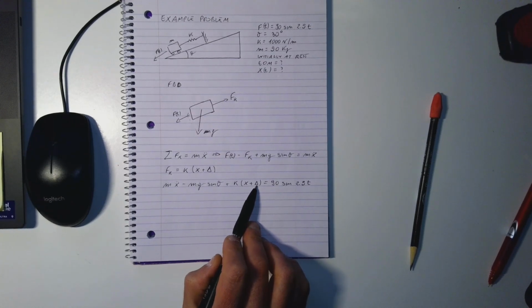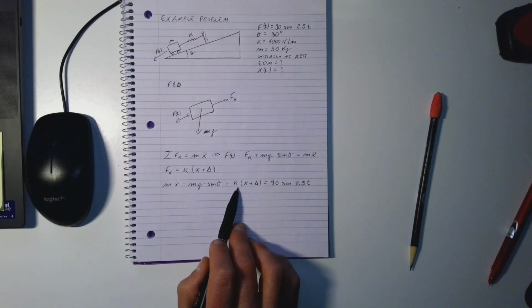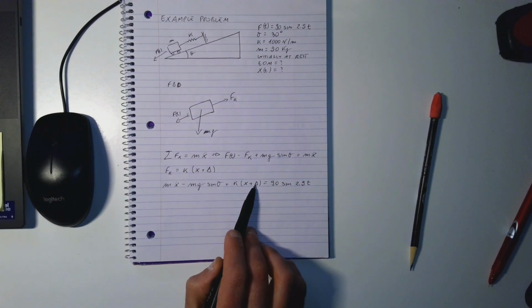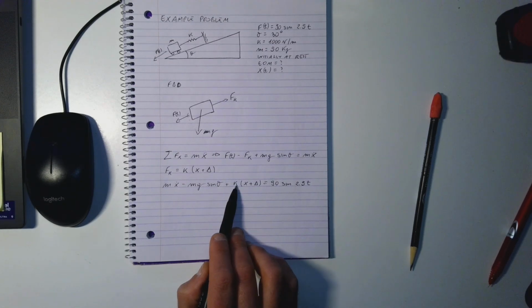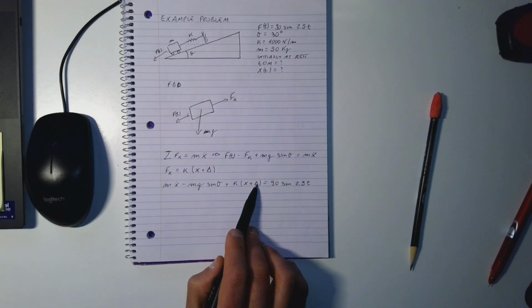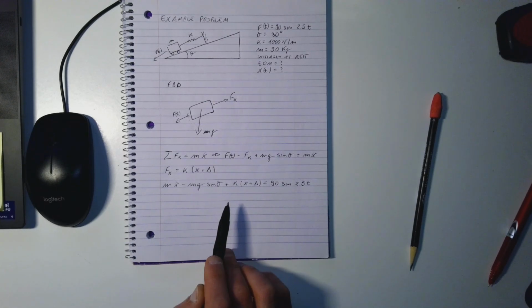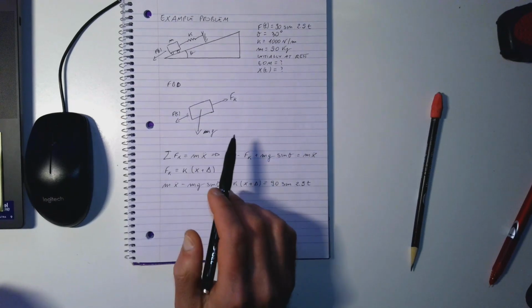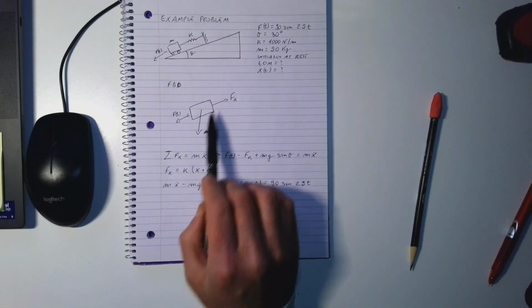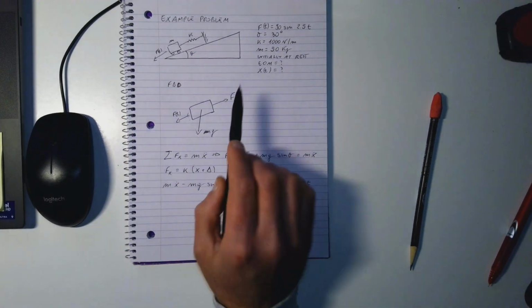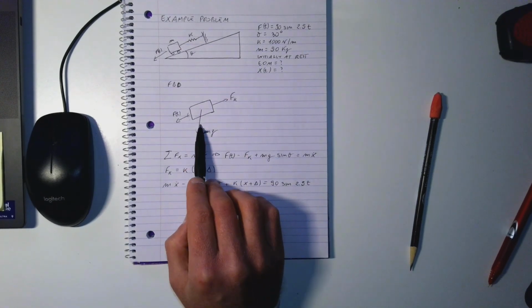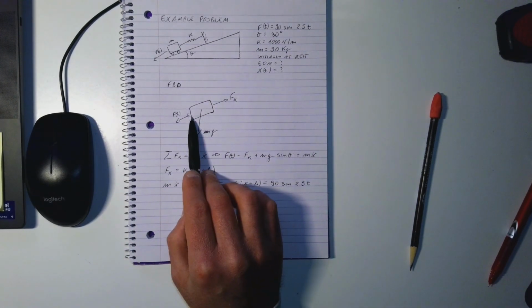Like this delta, we multiply by k. So that's correct. We can look at the product between this k and delta. Why do we need to look at this product between k and delta? Because what we should do now is look at the static deflection of the spring. Basically we have to look at the static equilibrium between the force of the spring and the component of the gravity in the direction of the motion.